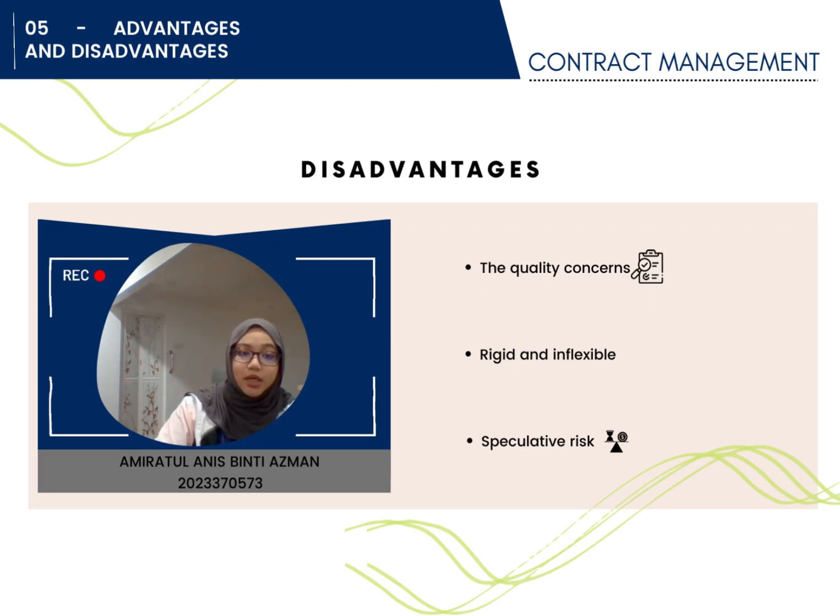The second one is that the design and build method may have the disadvantages of being rigid and inflexible when it comes to accommodating changes or alterations to the design. This is because it's possible that the client had little influence during the design phase, and may not be able to change the design once it has been approved and the construction has started.